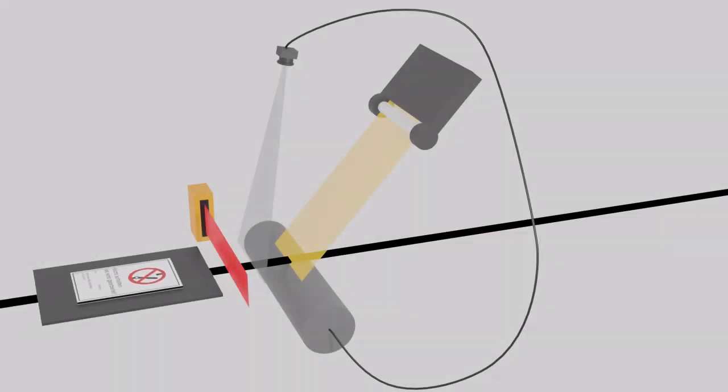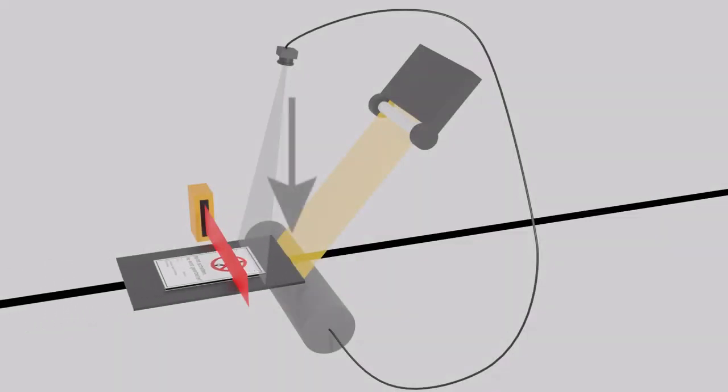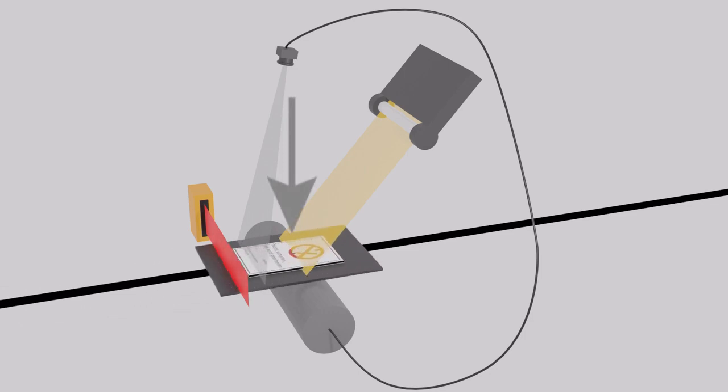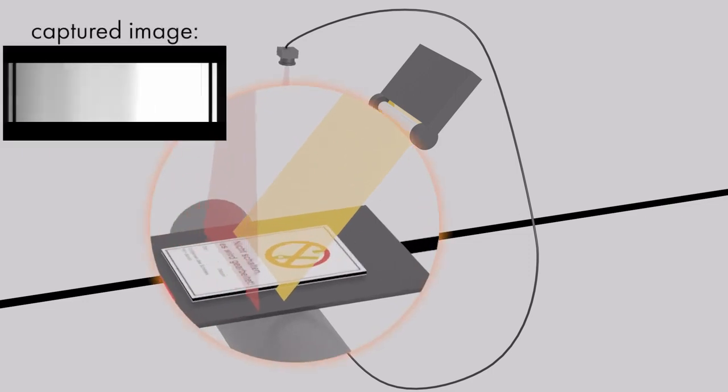For this, move the object to be inspected under the light source. This, of course, requires that the light source is already aligned with the path of the object. Start moving the camera and look to capture the illuminated part of the object. If your setup is correctly configured, you should be able to adjust the camera in a way that all pixels are capturing light homogeneously.